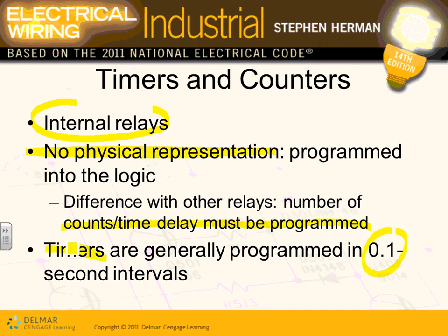When you have a timer, you're going to see in a second, I have an example for you guys, where I want to start this machine after 5 seconds. So you click a timer, 1, 2 Mississippi, 3, 4, 5 Mississippi, and the machine will start. Where does this timer exist? Nowhere. It's in the brain of the PLC, which is the CPU. That's the beauty of PLCs. If you don't have a PLC, you know what's going to happen? You have to have a big device called a timer in order to get this to work.